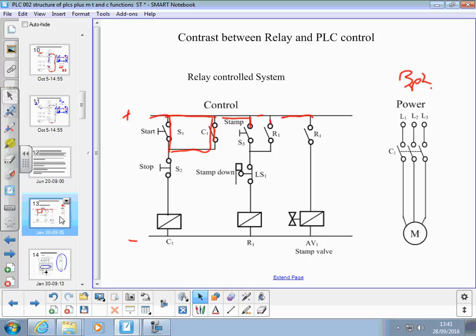Don't get the idea that you never have to do any wiring to change a PLC, because if you're adding a sensor or adding an extra output, you certainly do. But generally, how things interact with each other can quite often be done by changing the program in some way. So it does reduce the amount of work when you want to add functionality.